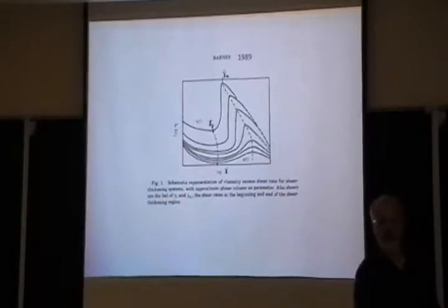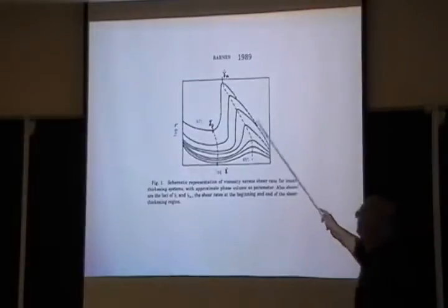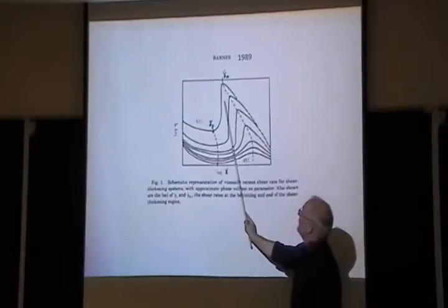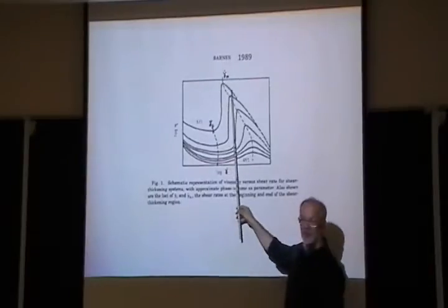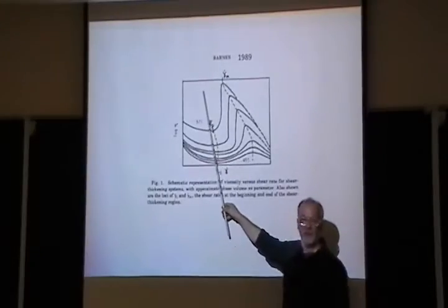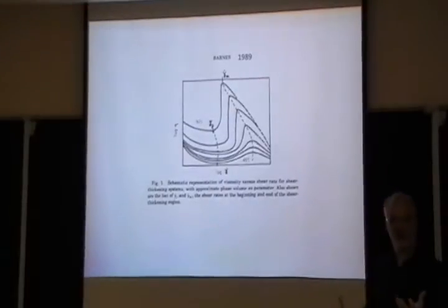So for cornstarch, it is a near vertical jump. Now notice also that this jump location, where at a certain shear rate the viscosity goes up, moves slowly to the left. So you don't have to push as fast if the concentration is high. Right?